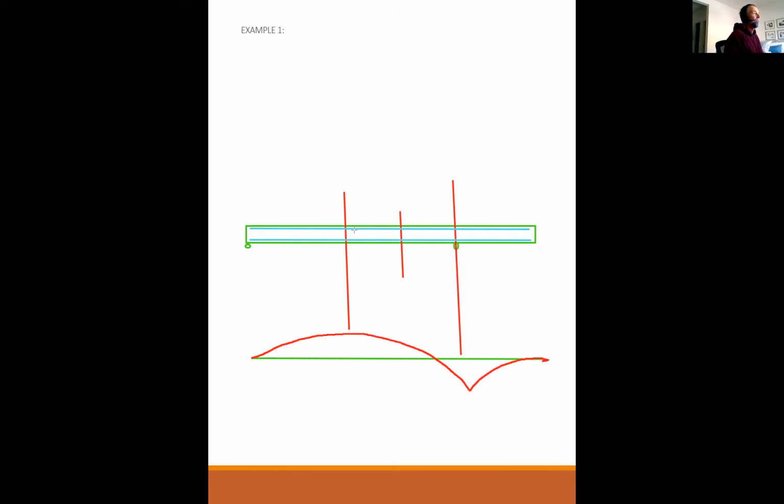If I had just ignored that compression steel altogether, what was the difference? It was only like 7%. So the other half of the answer is, even if you really did have a doubly reinforced beam, you could always ignore the compression steel if you don't really, really need it, and your answer will be conservative.